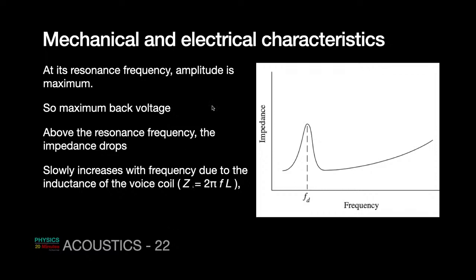Okay. So today we looked at some of the important characteristics of the dynamic speakers. One was we discussed the magnet and magnetic field. Then we spoke about the spider arrangement, which was helpful for us to understand the mechanical and electrical characteristics of a speaker, and we also talked about the geometries by which the voice coil is placed in the magnetic field.